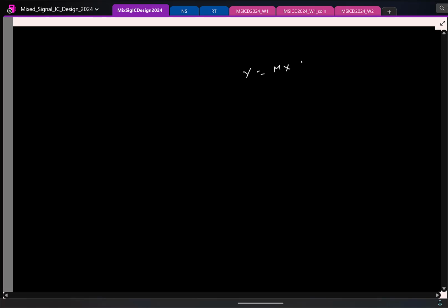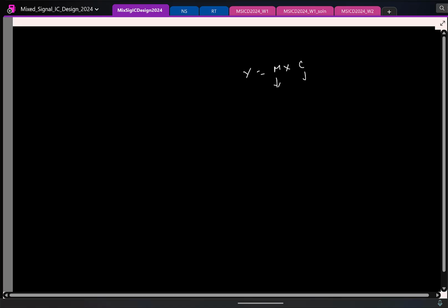So including gain error, offset error, and non-linearity, you will say that ADC is non-linear? No. Non-linearity is due only to non-linearity. We will not include gain error and offset error in the non-linearity. That is not a non-linear phenomenon. That's a linear phenomenon. It's a straight line y equals mx plus c, just that m is different from what you want and c is not 0.